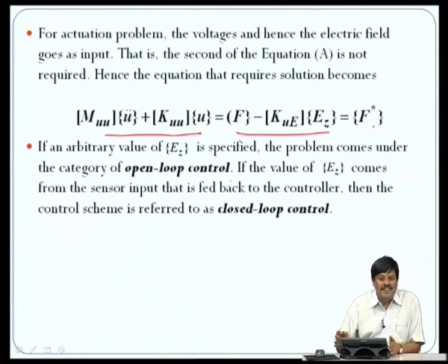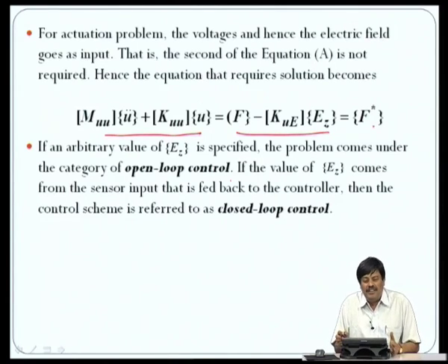So, as we see here, this formulation using the isoparametric element is a level higher and more sophisticated than the lumped approach we did. The lumped approach only gives us an approximate value of how the piezoelectric material operates, because we make the assumption that the sensor law and the actuation constitutive law are uncoupled.